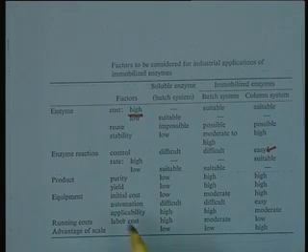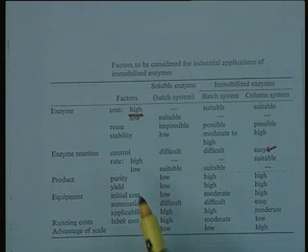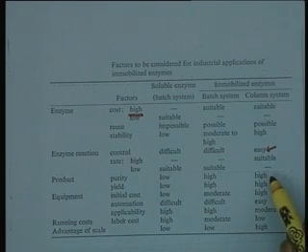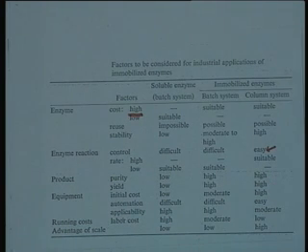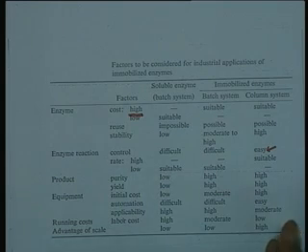or even immobilized enzyme batch processes, and the control is much more effective in the case of a continuous flow reactor using immobilized enzyme. Of course, the product purity also has a role to play in the decision making of the use of immobilized enzyme. Product purity can be very high in the case of immobilized enzyme used in continuous reactors, because there is no likely contamination from the enzyme protein, or some of the side reactions that are likely to take place, and the residence times are usually less than in the soluble enzyme or batch reactors. Because of the advantage of the smaller residence time in the continuous reactor, as well as the absence of any contamination from the enzyme protein, it provides you a product which is much more pure compared to soluble enzymes or an immobilized enzyme in a batch system.